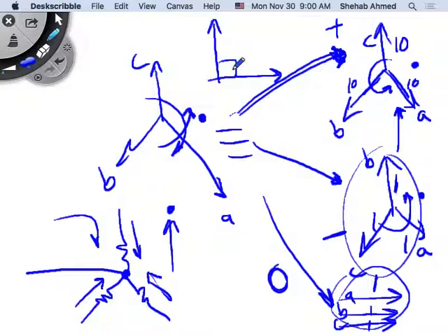What was that capacitor doing? Why was it starting? Yeah, it was creating this phase shift, because you only had a single supply, right? You had a single supply, but this capacitor is phase shifting the voltage by 90 degrees and applying it to a second phase. When you do that, you have two phase voltages that are 90 degrees apart. When they rotate, they generate a rotating MMF.